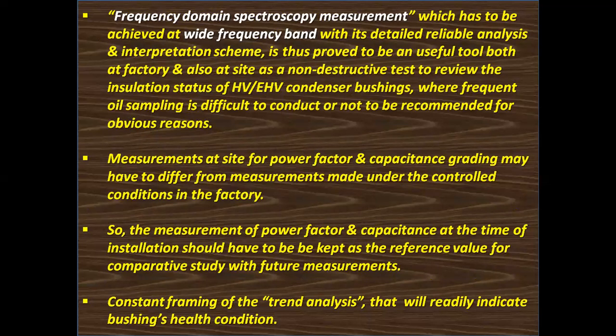Frequency domain spectroscopy measurement, which has to be achieved at a wide frequency band with its detailed, reliable analysis and interpretation scheme, is thus proved to be a useful tool both at factory and also at site as a non-destructive test to review the insulation status of high voltage or extra high voltage condenser bushings, where frequent oil sampling is difficult to conduct or not to be recommended for obvious reasons.